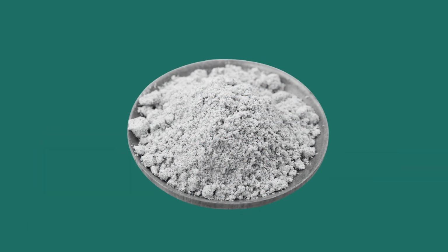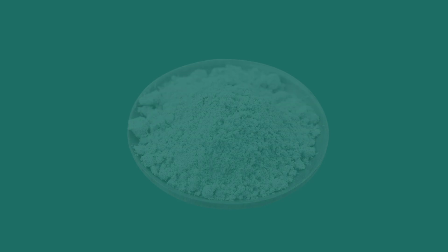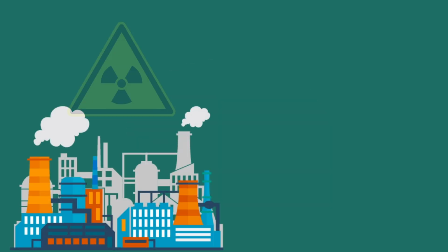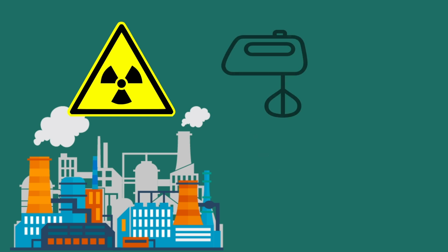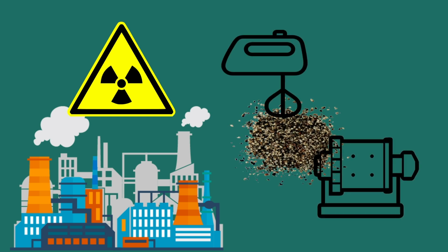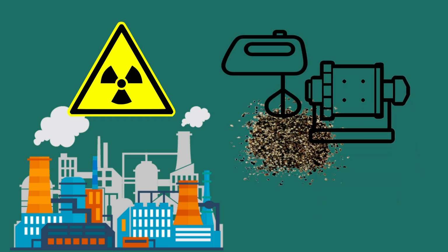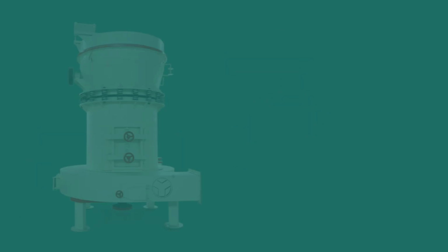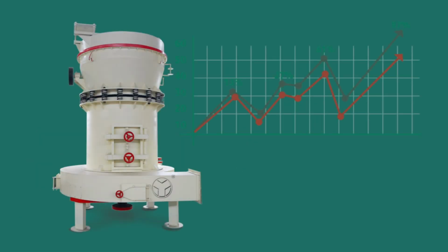In the existing process lines for production of reactor uranium and plutonium fuel, the initial powders can be first mixed and then pulverized, or mixed and pulverized at the same time. Ball or hammer mills are used for this purpose. However, such mills prove to be low efficient in pulverizing and mixing the initial powders.